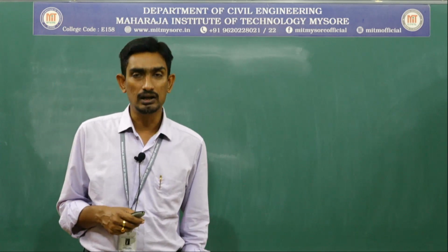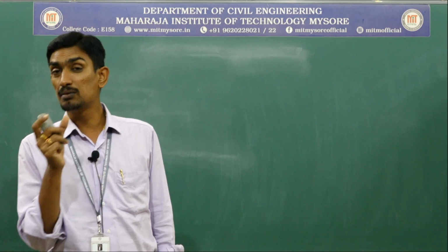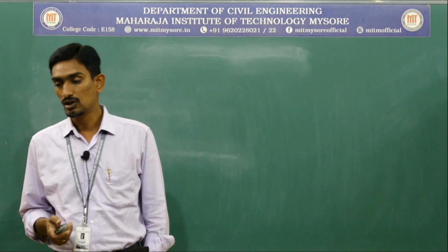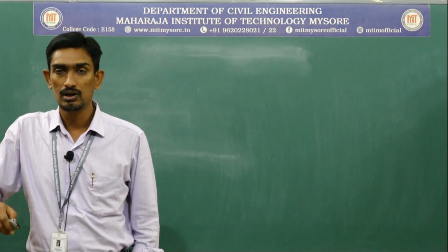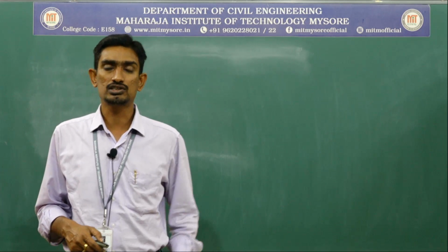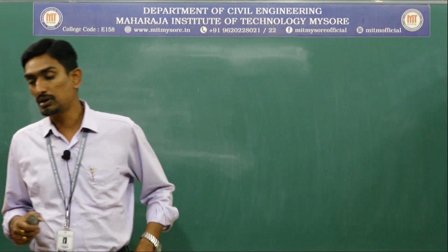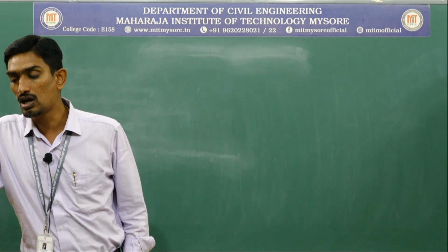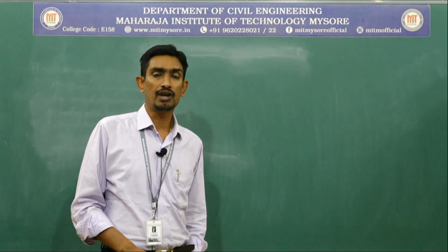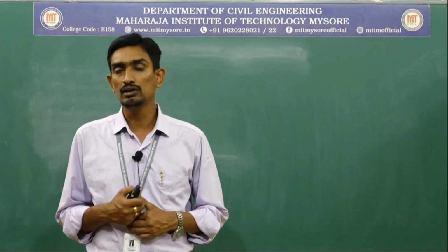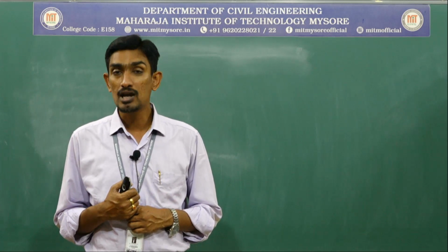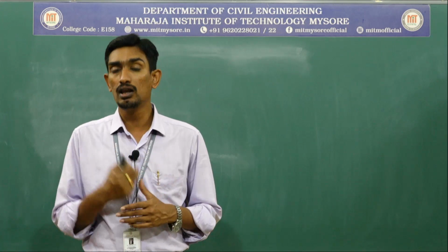You know what mud is. Mud means soil block. What is the meaning of stabilize or stabilization? First let me define, later on I will go to the other things. So first, stabilization of soil. As I told, what we predominantly use to manufacture the stabilized mud block is soil. So stabilization of soil is alteration of one or more properties of soil. What are those properties? For example, if you want more density, more strength, to make it more impermeable, or more durable.